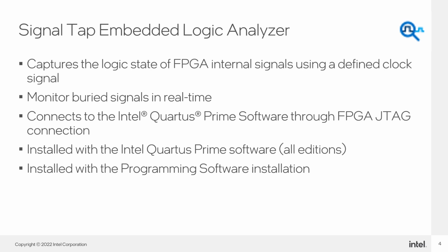Signal Tap Embedded Logic Analyzer takes the brains and features of a typical external logic analyzer and incorporates them into your FPGA design, programmed into the target device on your board. It is an embedded logic analyzer built using available FPGA resources, no I/O, board routing, or probe points required. The Signal Tap Logic Analyzer emulates many of the features of an external logic analyzer.